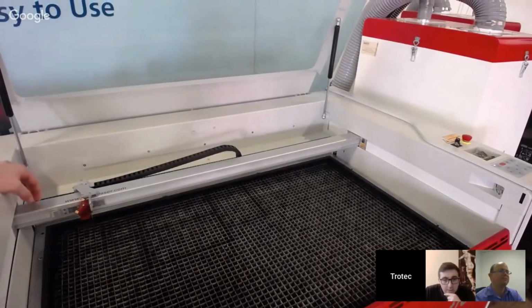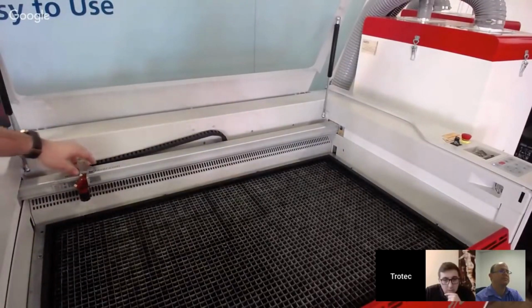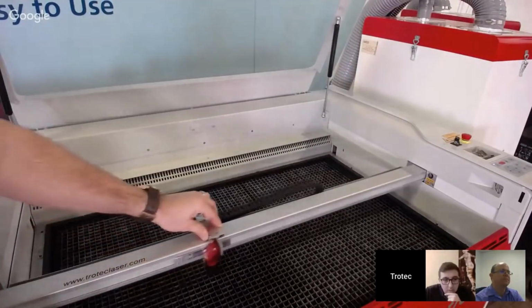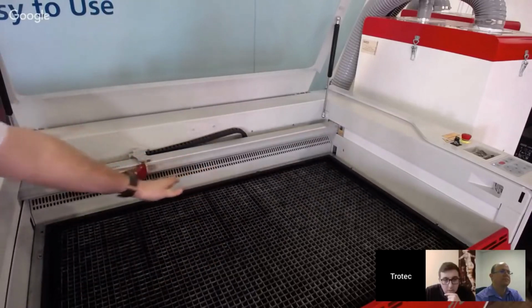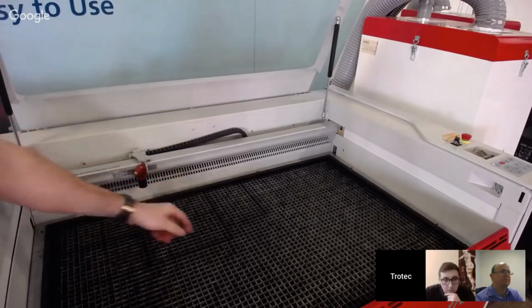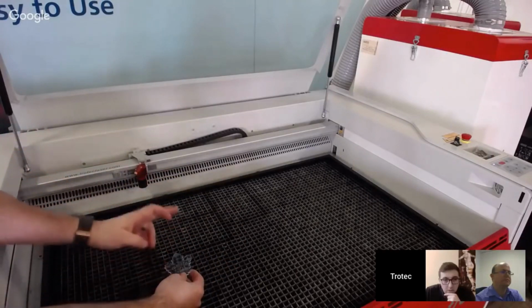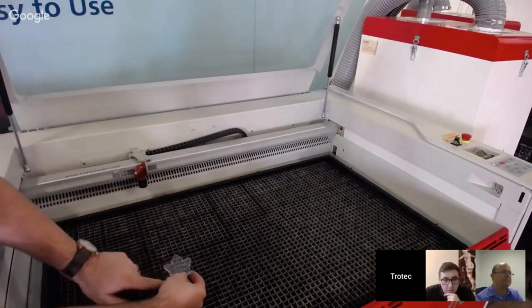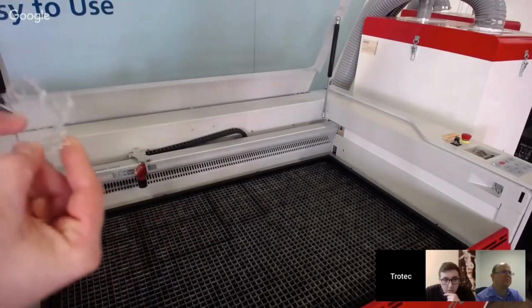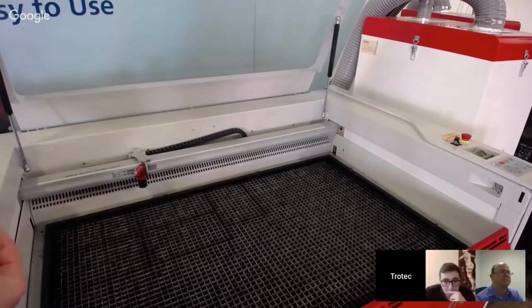Perfect. Thanks, John. Yeah, so just a visual representation here, guys. As you're engraving from the bottom here, you're going to be engraving upwards. Your vents here are going to be sucking the smoke upwards. So you want to start from the bottom because you're engraving. If you were to start from the top and that smoke is getting dragged across, those fumes are going to get caught in the actual depth of your engraving, which is why you'll get those sticky residues and discoloring of your engravings.